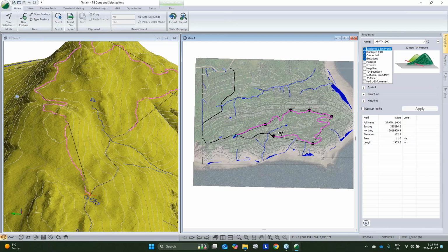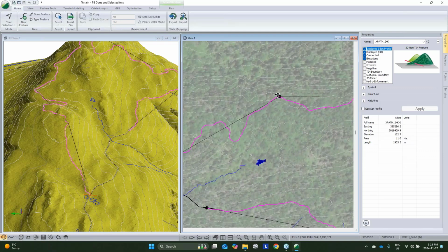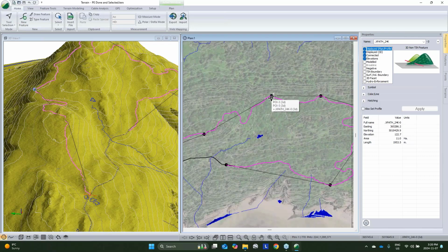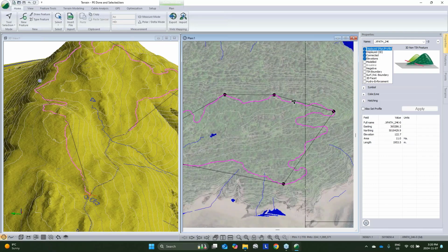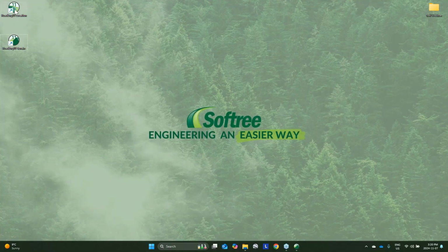We've run Path Explorer from point A to point B to point C. And while we're doing that, we've added some direction constraints as we come into those destinations or leave those points of interest, just so we get something that's nice and continuous. And once we're happy with this, we will switch over and open up Location, and we will do our design in more detail.